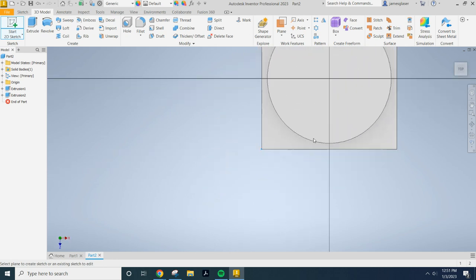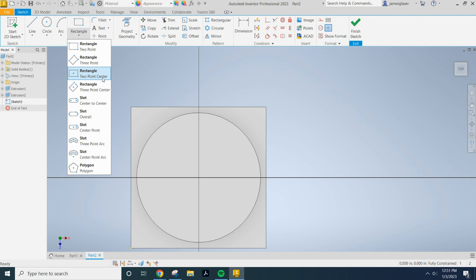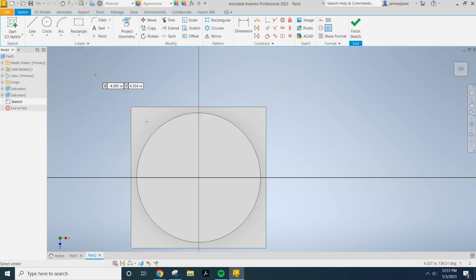I want that on that surface. Click it over, drag it over, make sure your view cube is reading top correctly. And we want to go ahead and drop a 2-point center rectangle on this thing. Now, it sometimes will snap to the grid, but you see how it's not going green? That means it's not creating a coincidence constraint.